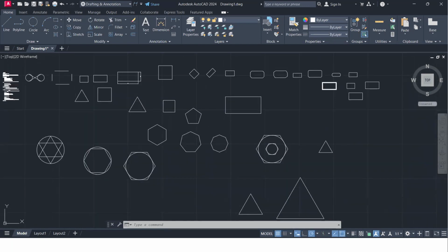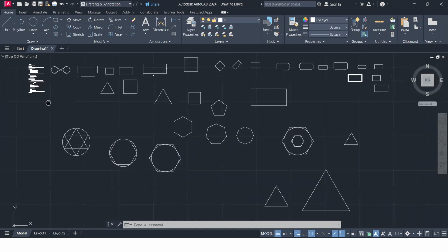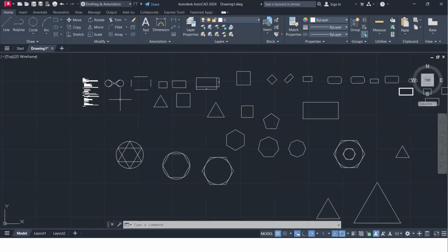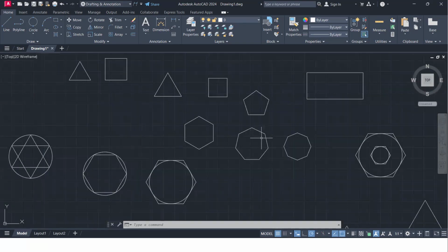Now I also talk about the zoom option. I also talk about the zoom all option. I talked about the zoom all option as a form of setting the limits, right? When we specify your limit area and then show the limit area, then you can use the zoom all option, right? And there are other options for zoom, so which ones are important for you? Just check this out.